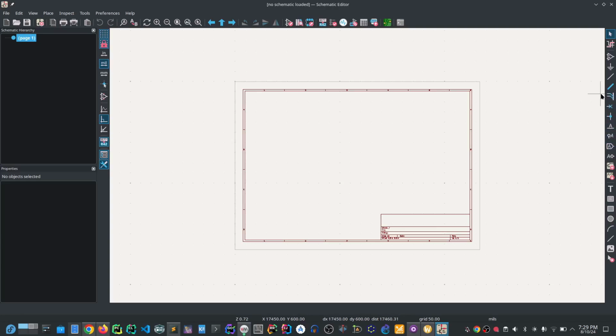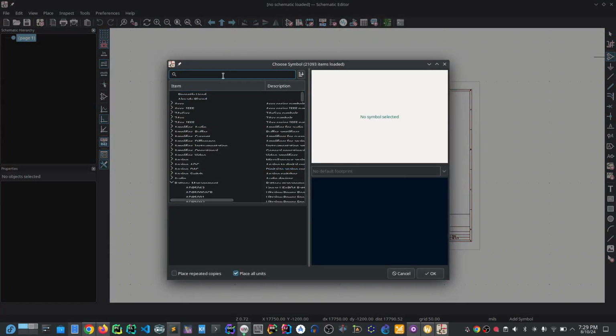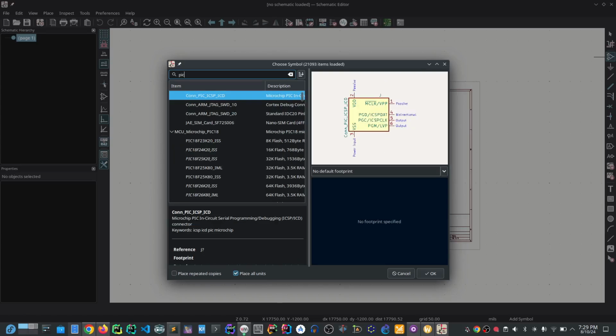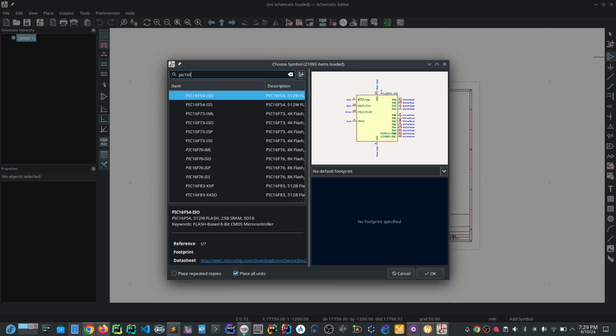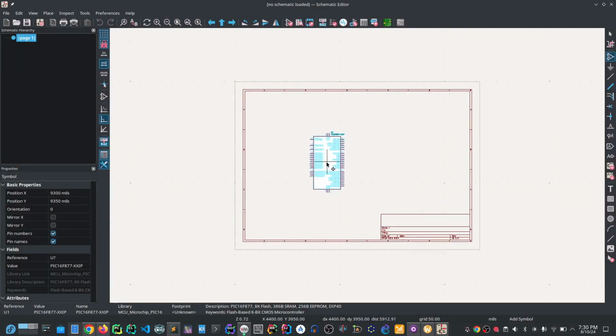So I'm going to be discussing this. Just to show you, here is a component panel where you can load all your symbols and components. You can drag any of the components and search for any of them. If you're looking for a resistor, or you're looking for your PIC, there's a 16F8. You can see all those 16F8s here. Anything you're looking for, you're going to see all these things and drag them. Then you drag them, say add the component, and drag it here.